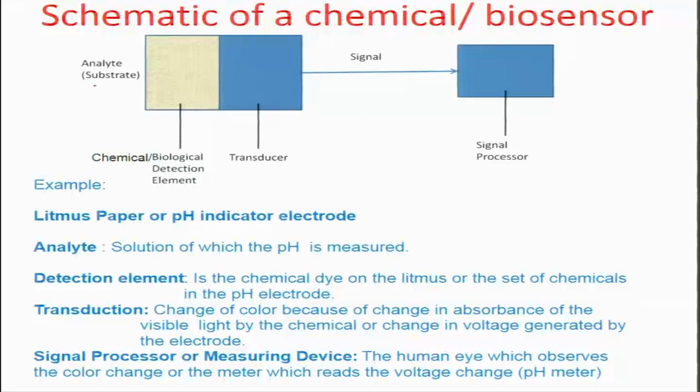We were talking about sensors and the sensorial model of an analyte being investigated through a recognition element, which is generally immobilized on the surface of an otherwise constructed detector. The detector typically does a transduction, in which the chemical signal is converted into another machine-readable signal, which can be electrical or optical.